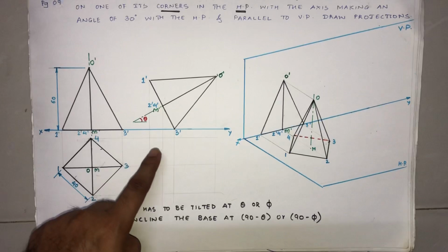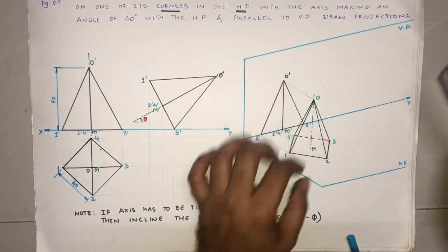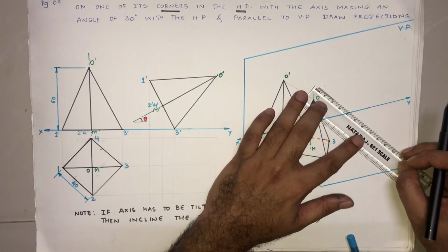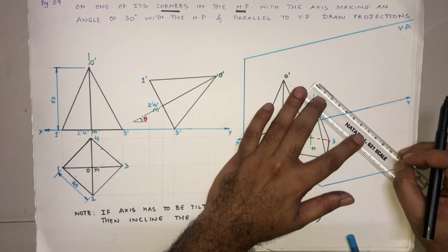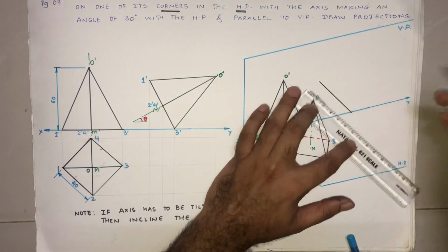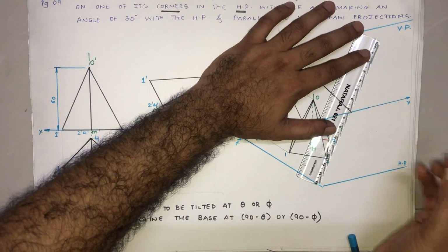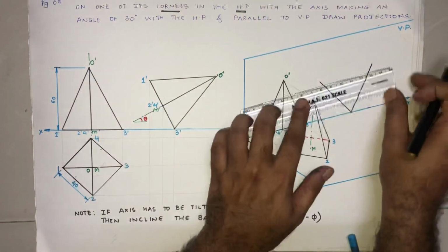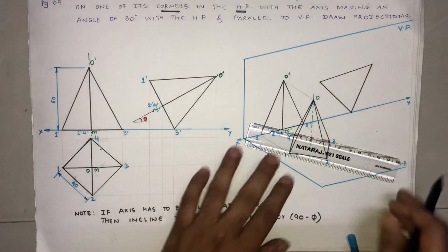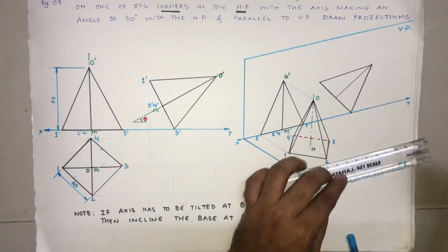Now why, sir, why did we do this? Guys, it was very simple. I'll just show you. Say we're going to tilt this. So I'll just measure this somewhere around 4.4. I'll take some point, and here let us say that this is the view that we have tilted. Once again, this view we have tilted like this. Remember, the view is not tilted, the solid is actually tilted, and hence the view also is tilted.